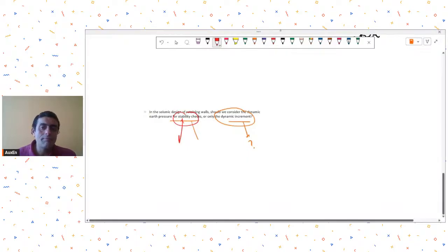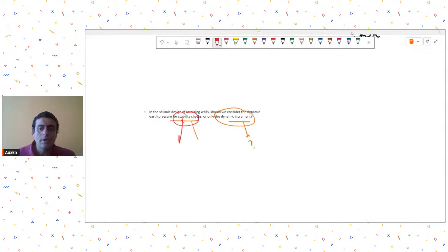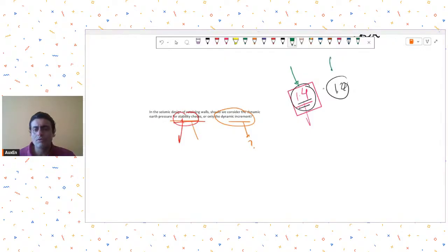In stability, I'm not sure at this point that when you are doing the stability check, are you allowed to, let's say, go for some reduced factors or not? That I'm not sure right now. For example, we have some 1.4 factor for overturning. Am I correct? I'm slightly confused. Is the stability factor 1.4 for overturning and 1.2 for sliding? So, under the effect of earthquake loads, do these factors remain the same or can we reduce these factors slightly? This point I'm not sure about right now.